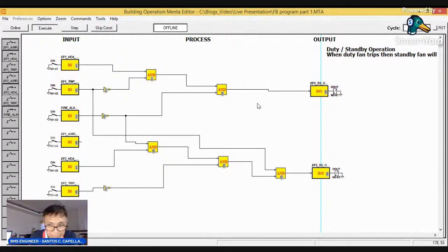our equipment stops because we said that if there is fire, this ventilation fan should stop. Okay, now let's remove the fire. Okay, so again, let's say our EF1 is running, then this guy, the technician, goes to the panel, then removes the EF1 selector switch from auto. So from auto, he removes it and puts it to off.